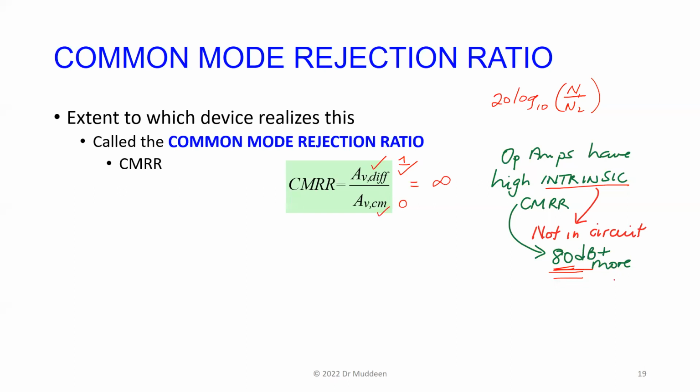To find the actual ratio, divide this by 20. So that's 4. And what is 10 to the power 4? Well, 10,000. So even with a 741 op-amp, if you could get all the resistances equal, it would discriminate between the differential voltages and the common mode voltages by a factor of 10,000, 10 to the power 4, 80 dB, right?